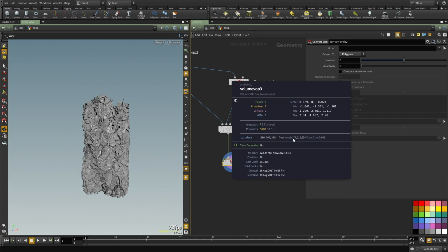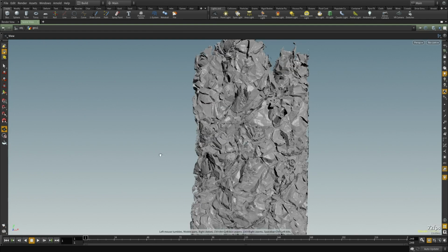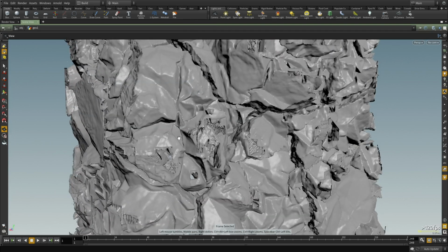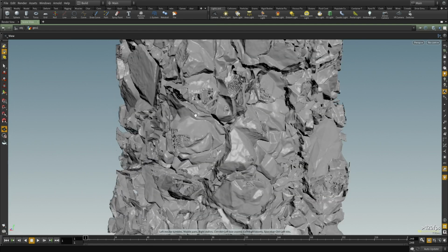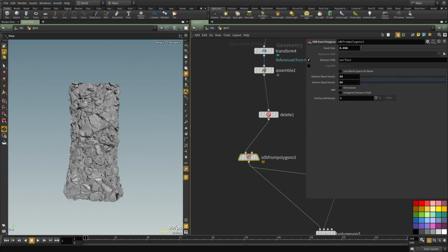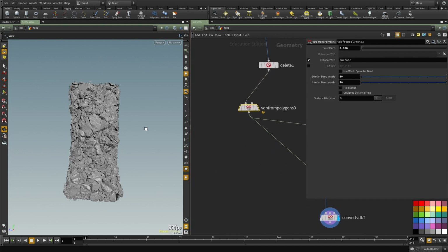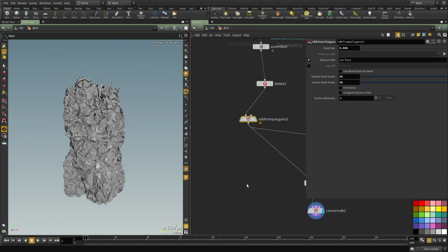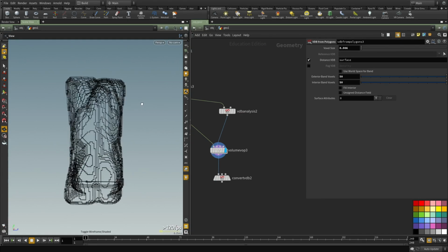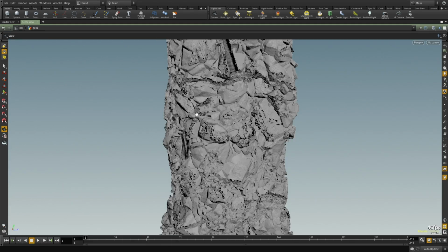Yeah, it's 74 million voxels. And look at the result. Now, obviously, there are gaps that we're starting to see, and by just adding a little bit of banding, extra voxels, if I look here and click W, you can see we can add a little bit of room, and that will fix all the issues.